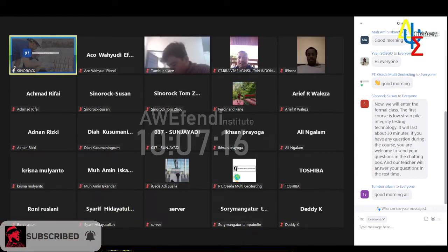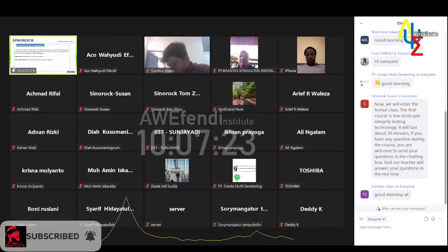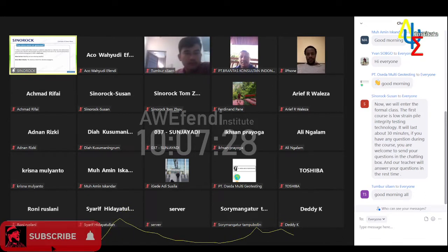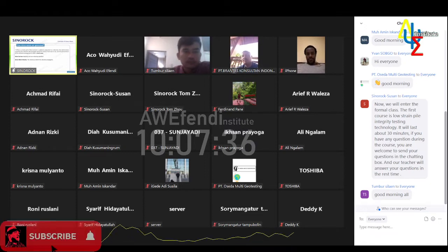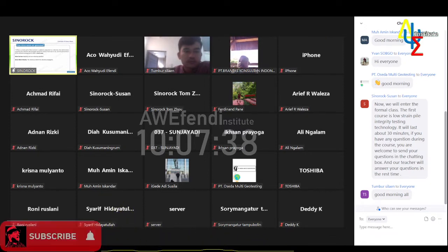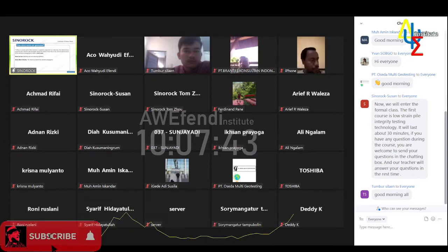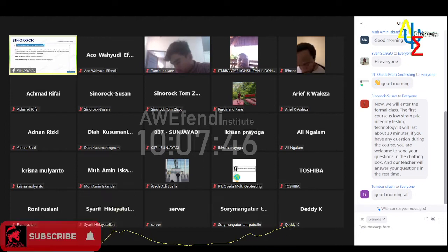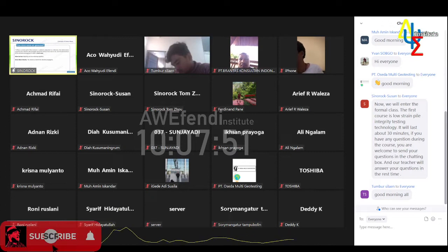The first part is the concept of stress wave, which is the most basic principle of low strain, and explains why we use low strain method to test the integrity of the pile body. How does the stress wave come into being? When a disturbance suddenly occurs in a certain place of the medium, the deformation caused by the disturbance will spread along the medium from near to far.